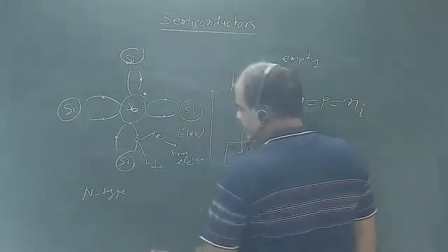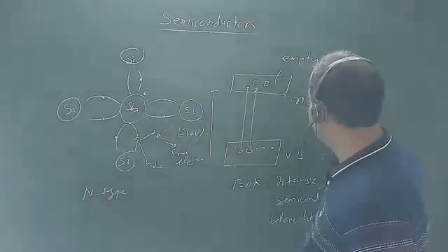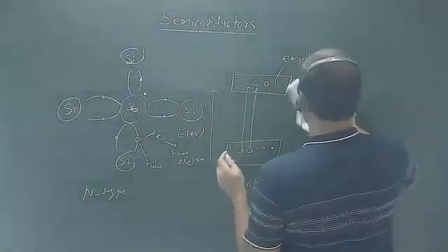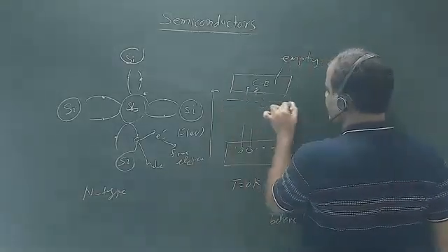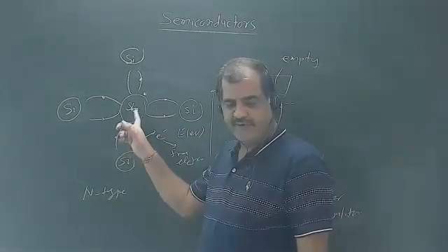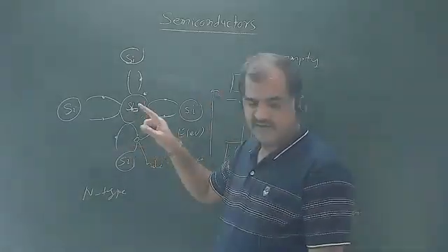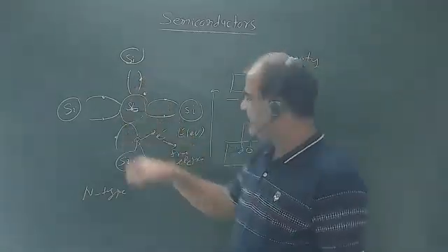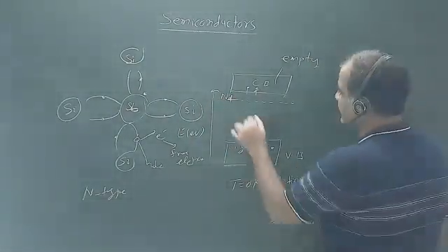n-type semiconductor. So what will happen when you dope, replacing the silicon with some element of the 5th group? These electrons are very close to the conduction band. So the energy level of this donor atom, these are donor atoms. In the case of n-type material, if you are adding a 5th group impurity, that element will give its electron to the crystal. That's why this is called a donor, and I will represent it by Nd. So these are donor atoms.